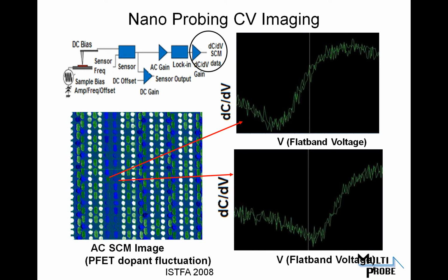We need to actually have test structures made which are intentionally misdoped and spend more time looking at them. So I'm sure you'll see more papers emerge as we calibrate these effects. But the point here is that there's a very measurable threshold difference or flat band voltage difference, which would result in a very strong threshold effect when the transistor was operated. So when that device was turned on, you would expect to see a significant voltage shift in its on characteristic. And this is being measured with capacitance and highlighted by an image, and then you go to the CV curves.